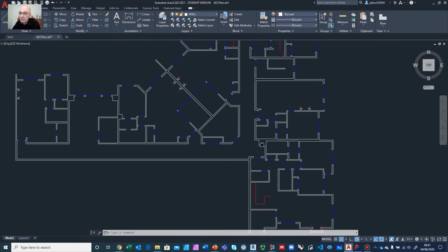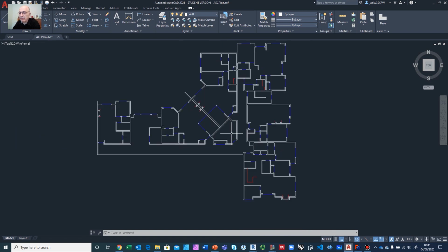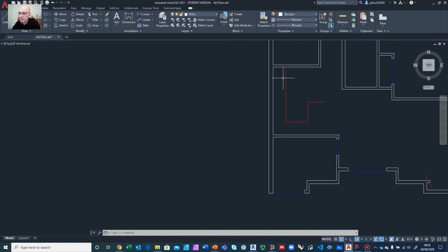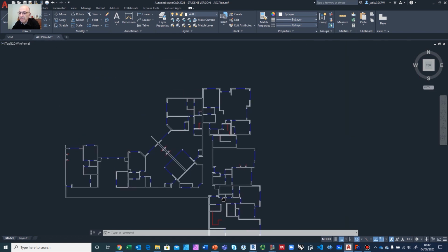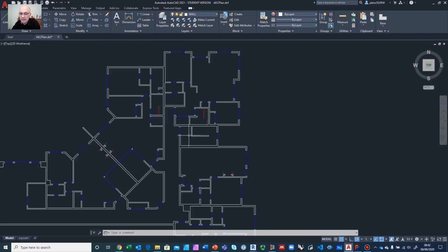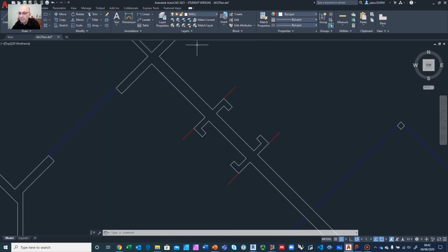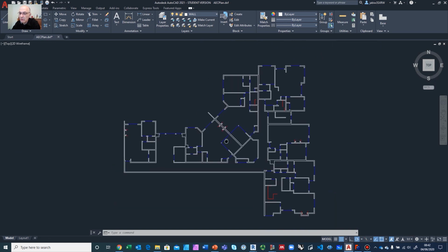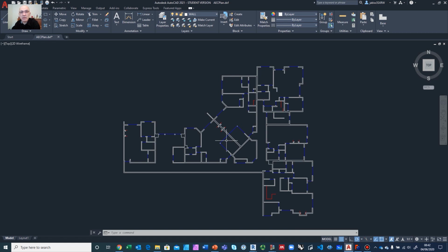Okay, now the third thing I did was this drawing had a lot of furniture, bathtubs, toilets, kitchen sinks, etc. So I removed all of that. I deleted those layers. We don't need them for this kind of work. But on purpose, I left some lines that are non-manifold, loose edges sticking out, and I put them on a layer by themselves called mistakes, and they're indicated here in red. So things like this, I just wanted to test that my script can actually clean that up and remove it from the drawing, as we saw before in the presentation. So you see these red lines, and here as well. They were part of the drawing, and I just left some fragments of them just to test and see what happens. Okay, so how do we get this into Dynamo and Topologic?